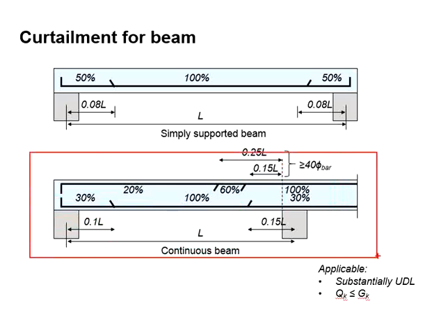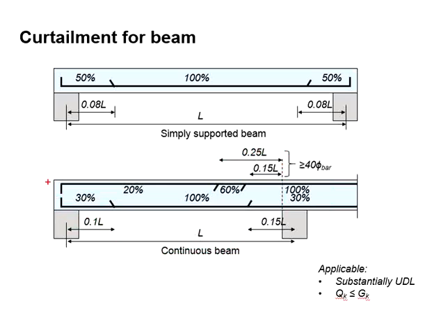Taking this continuous beam as an example. This is the beam here, and you will have an incoming beam here. This is the incoming beam. You expect there will be reinforcement for this beam. There will also be reinforcement for this incoming beam. Ultimately, the reinforcement should meet at their joints. Imagine you are providing the full amount of reinforcement bar entering the support, whereas for the incoming beam you are also providing the full reinforcement bar.